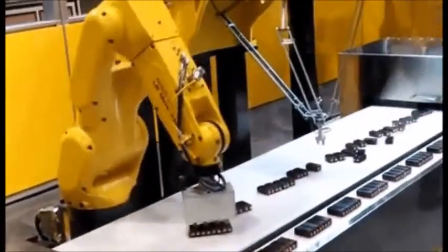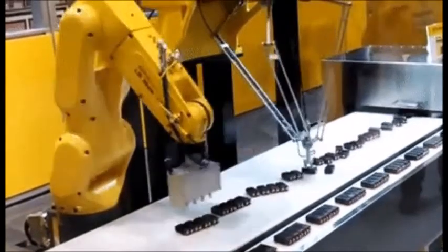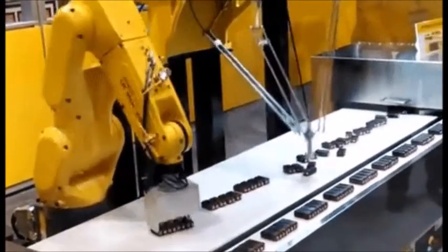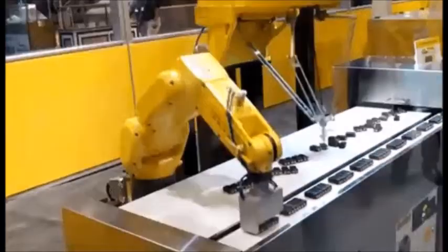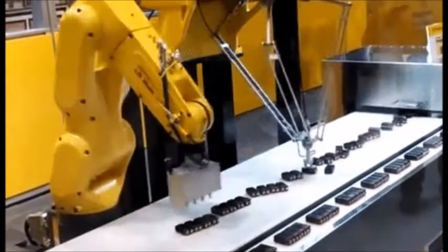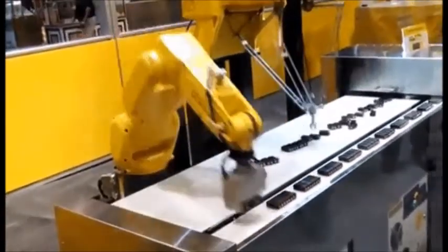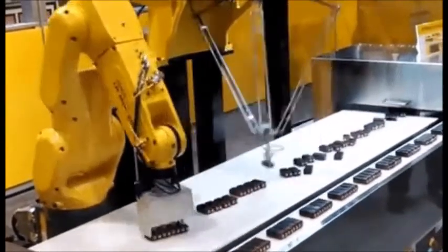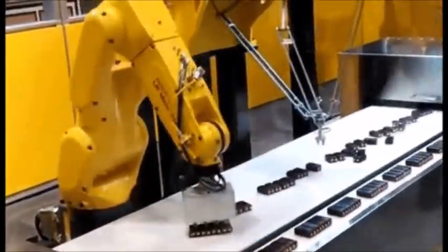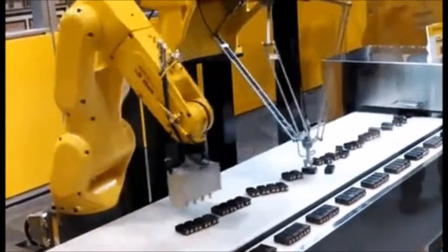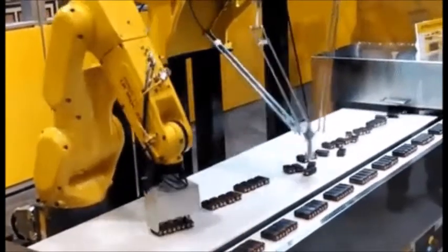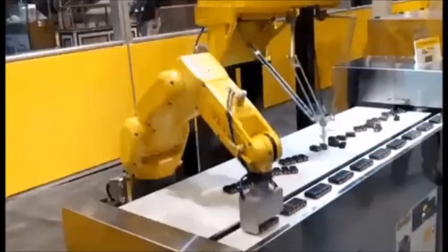As we can see over here, the function of the robotic arm is to pick an object from one conveyor belt and put the object at another place on the other one. For such applications where precision is the most important factor, we use stepper motors since they have the ability to rotate in small discrete steps in accordance with the applied train of pulses. These trains of pulses are nothing but digital control signals generated by some controller.